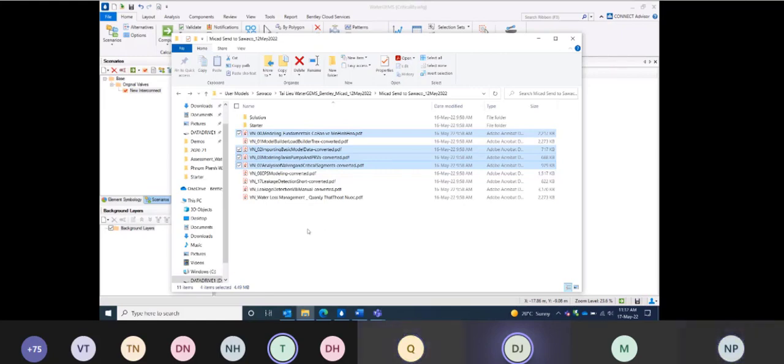So if you have the valves in your network, in your GIS, or maybe already in your model, then all you really need to do is open up criticality and click compute. So it's very, very simple, and it takes no time at all. So that's why it's such a good feature, because there's very little setup and there's very little information required. And we have the tools there, as I showed you yesterday with the assign isolation valves to pipes tool to do it automatically. So yesterday was kind of an introduction. And then today we get to some of the more in-depth ones, as I said.